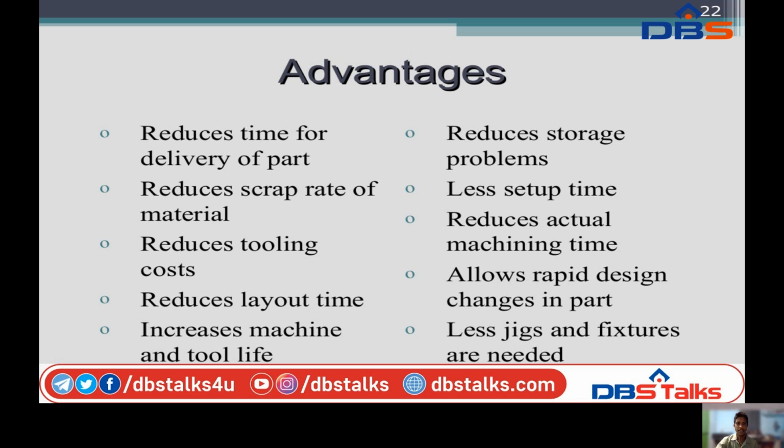Advantages of NC control: reduces time for delivery of a part, reduces scrap rate, reduces tooling cost, reduces layout time, and increases machining and tool life. First of all, reduces time for delivery of a part. Why? Because we are following numerical control, not completely depending on manual labor.